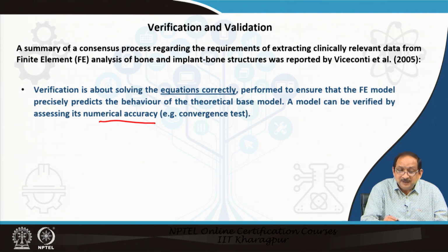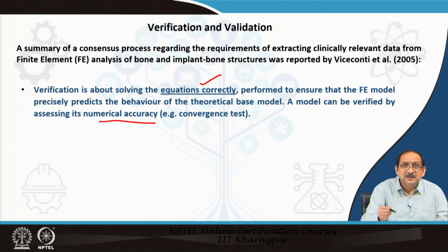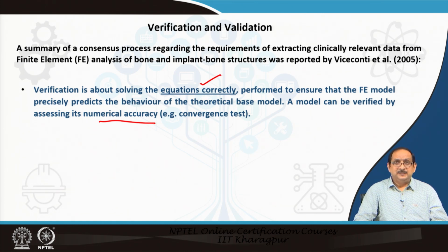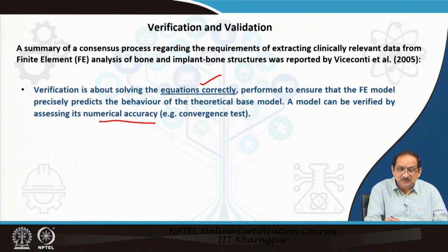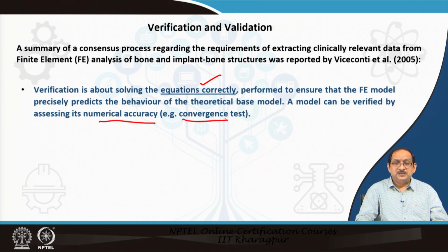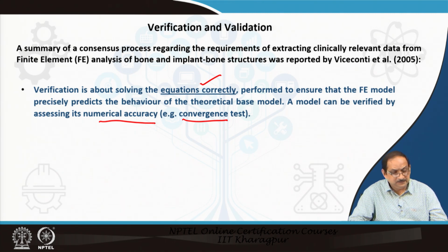So, verification is about solving the equations correctly, and we can employ the convergence test to verify the results of a finite element model. How sensitive is the model to changes in element sizes, for example?